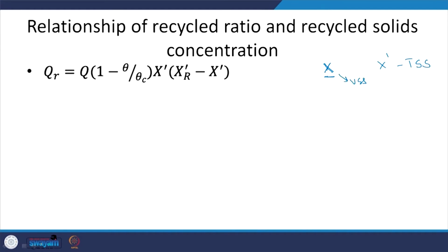And for a particular wastewater, based on experience, you can know the ratio of VSS by TSS, or the ratio of X by X dash. Let us say 0.6 or something like that. Based on that, you can replace X with X dash. That is why we replace this.